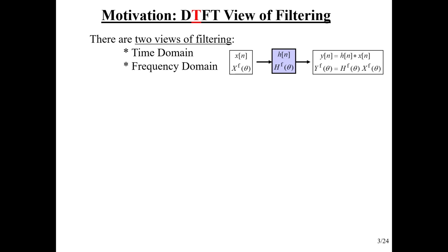I said this is an FFT-based way of implementing an FIR filter. So we're thinking about implementing the filter over in the frequency domain. Of all the standard ways of implementing a filter, there's just three that you really should know about: convolution, recursive solution of a difference equation, or the recursive solution of the state space model.